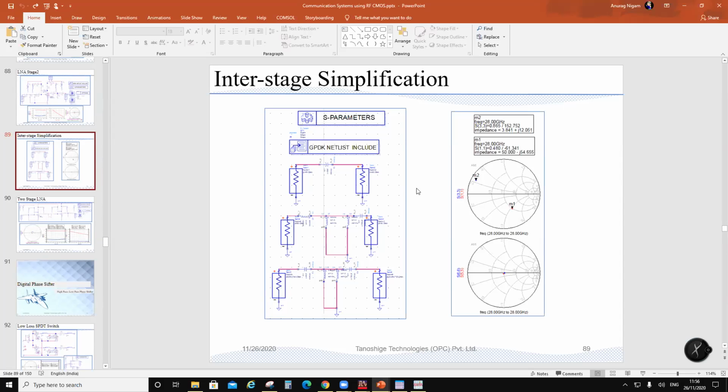Then the transistors are going to be conjugates, so you replace this 50 ohm with the conjugates. And conjugates is the normalizing impedance in ADS. So all you do is put these conjugate impedances and build a CLC or any other topology such that both matches come to the center. So what is happening is you are matching both the transistors.